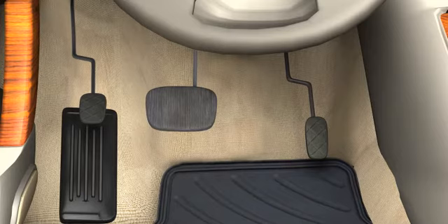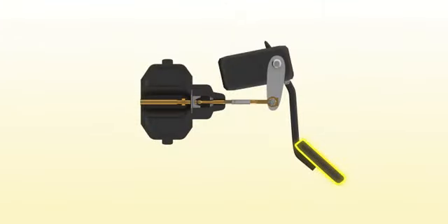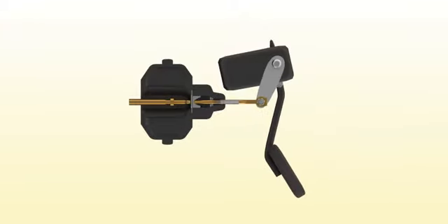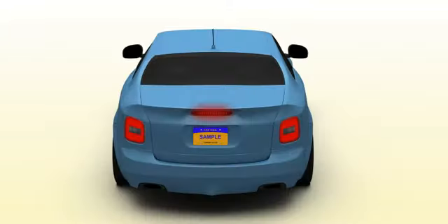Braking begins when the driver presses on the brake pedal. The pedal is a lever which increases the force applied by the driver against the brake pushrod. The movement of the pedal, which is monitored by the brake pedal position sensor, activates the brake lights. Pedal movement is also used for the anti-lock brake system, the electronic stability control system, transmission control, and other systems.